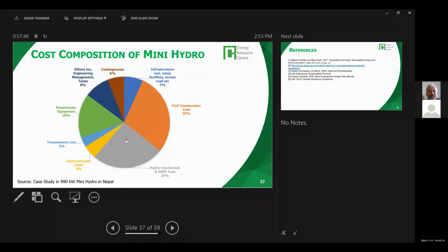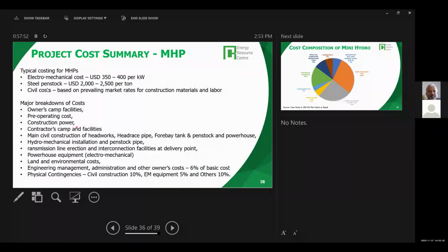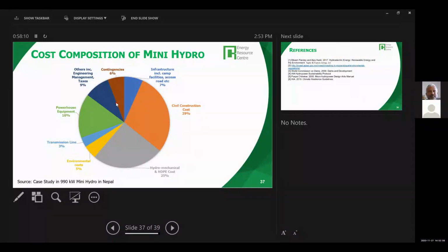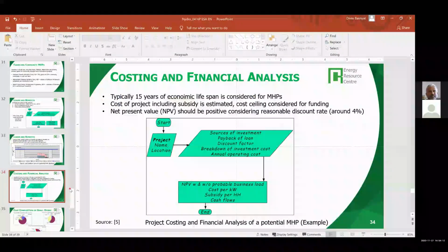So now if you want to reduce the cost, you have to look at this. Basically, you have to do a rate analysis. You have to get the unit market rates for the materials, cement, sand, steel, reinforcements, labor, and other things that have to be prepared. This will be part of the feasibility study. We will also consider it later. Okay, I plan to cover this much today.